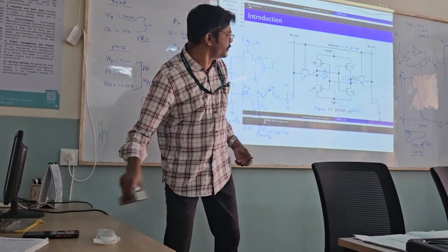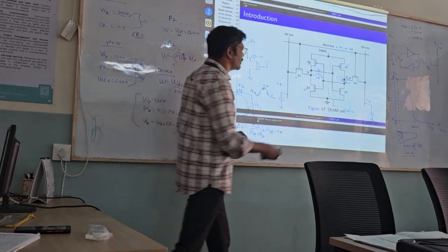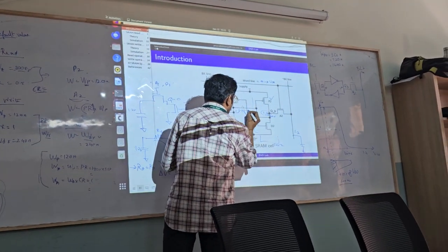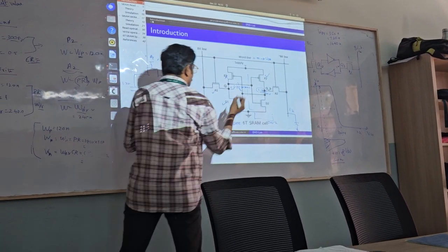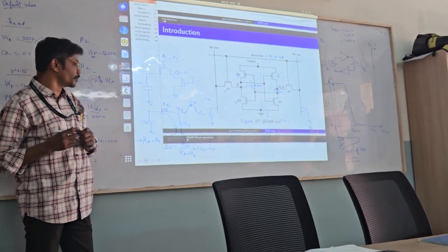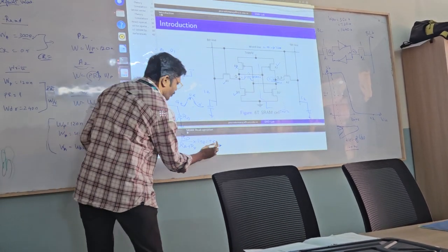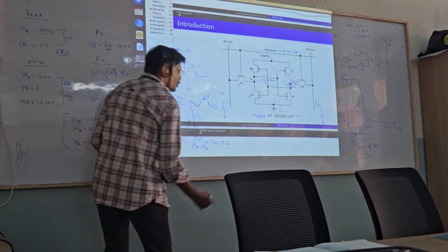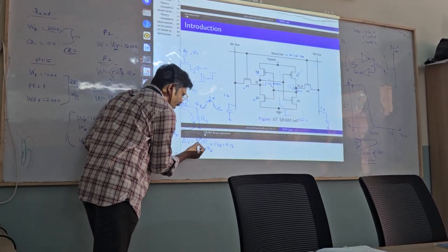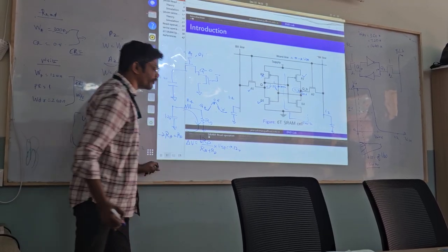Okay. So now to perform this, how do I ensure that this bump is not reaching 0.6, but rather I want to fix it to 150? What is the idea behind this particular value being reduced? How do I reduce this value of the bump to 120 millivolt? I have this formula. What am I supposed to do across this formula so that instead of getting 0.6, I want to make it smaller? Reduce RD. Yes, the best way is to reduce the value of this RD, due to which the total ratio will end up having a value of 120 millivolt.